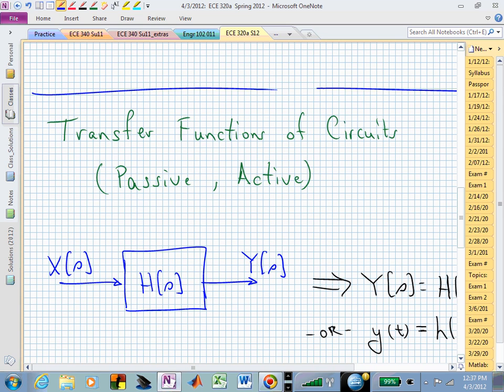You need to know how to model signals and how to find system descriptions, and in this case in particular in the form of a transfer function. In 340 you might see those as, and here you do too, differential equations. You might put them in a state space representation. There's all sorts of ways of modeling your system. In this discussion we are treating it as a transfer function, capital H of S. It's coming from a linear time invariant circuit, which means that it's now simply a ratio of polynomials in S.